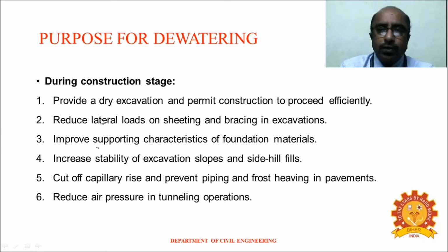Also, in some cases, we can reduce the lateral loads where we have gone for sheet piling or bracing in excavation. Also, we can improve the supporting characteristics of foundation material, that is the soil material.